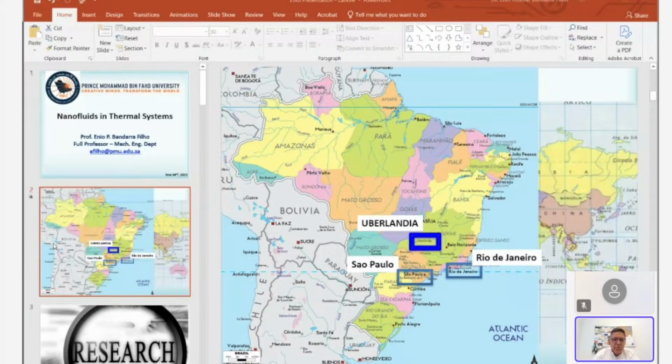Here you can see the thermal conductivity results according to the time and the temperature. We conducted some experiments from 10 degrees up to 50. The blue one here is the base fluid, in this case water plus ethylene glycol, mostly used in car radiators. And here are our experimental results. This dashed line is the curve obtained by correlation with the Engineering Equation Solver, a software.